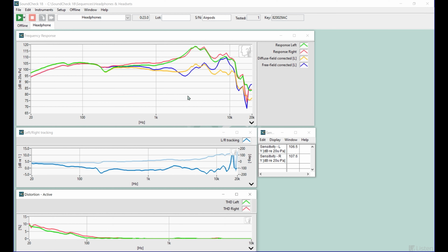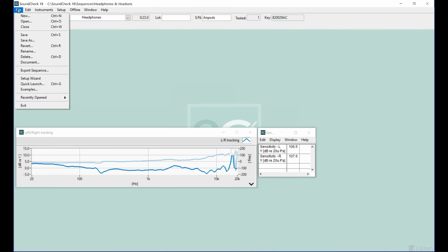And what I like to talk about in my distortion seminar is normalized distortion, where we actually take into account the linear response and how it filters the distortion response. If we did that, you would see it would be well below 5%. So that's just the nature of the high pass filter of the headphone. So pretty good headphone. And certainly if you want to put limits and calculate pass-fail results on a variety of things, you're more than able to do that.